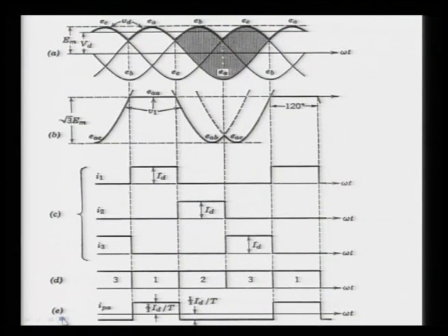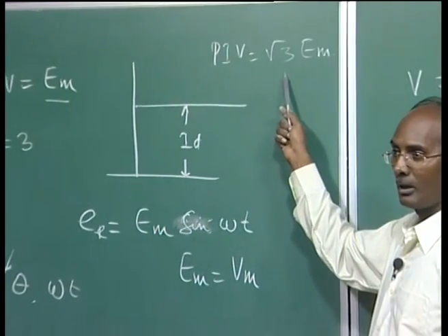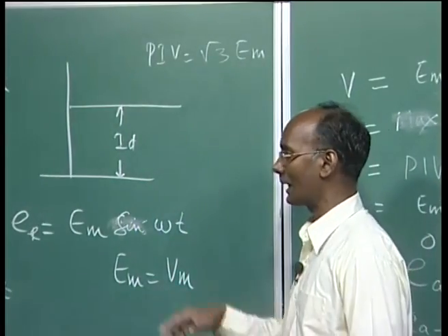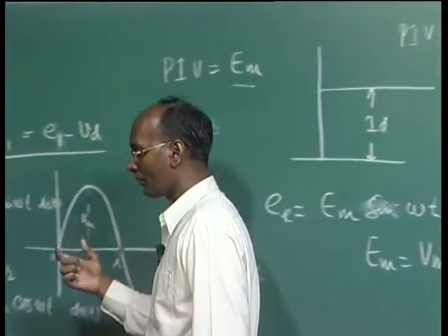So, this is a very rough analysis of the 3-phase one-way circuit, but it is not used because it has so many limitations. As I said, the DC current is appearing in your secondary, and also the transformer is not properly utilized, but the peak inverse voltage is not double, so compared to others it is still less. We can also calculate the power of the valve.